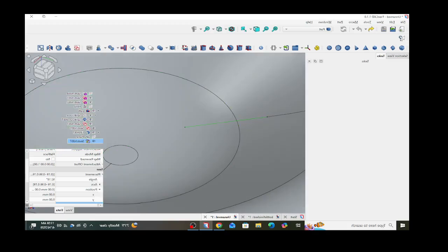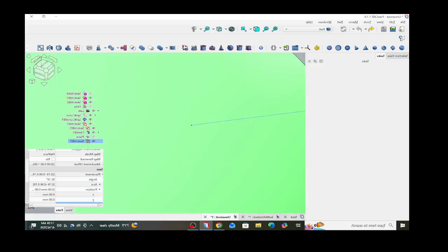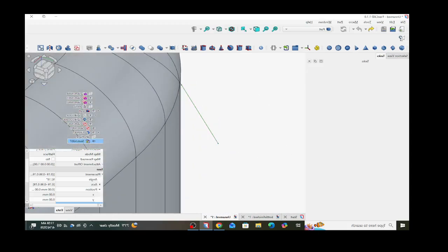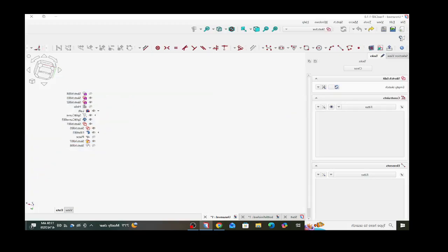And make sure you pick out a line, the line that touches the end. Excuse me, we'll start from this end because, yeah, there we go. Less interference. So you pick out the point at the end of the line, create a new sketch, normal to edge.